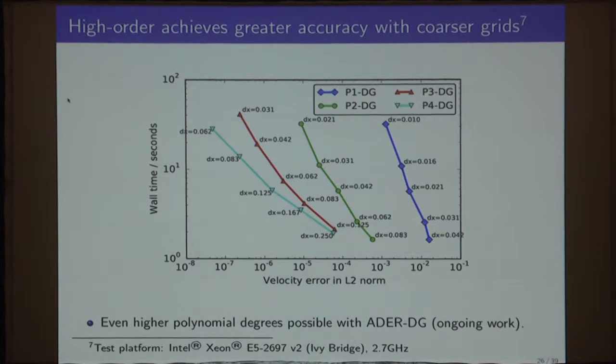So once again, it's reinforcing that by going up in order, you're reducing your time to solution. You're getting a more accurate solution, and it's requiring less memory. If you look at low order schemes, you can see here that the mesh size is tiny, and the results don't give you very good accuracy. And I guess the question, even when we're applying this further downstream, is what accuracy we actually need when solving the wave equation in FWI. So there's going to be some experimentation there.